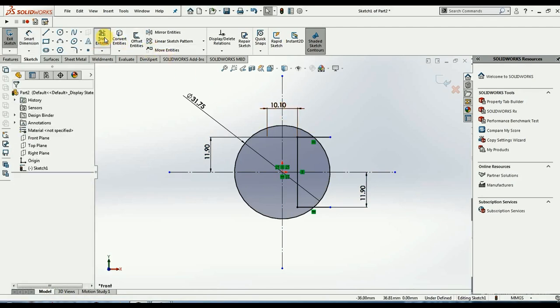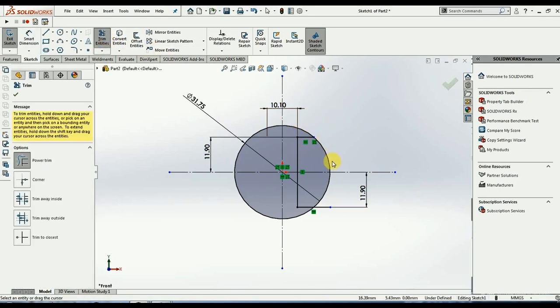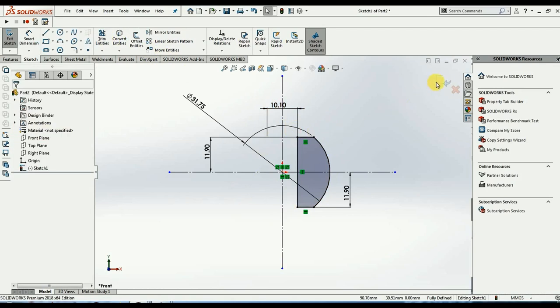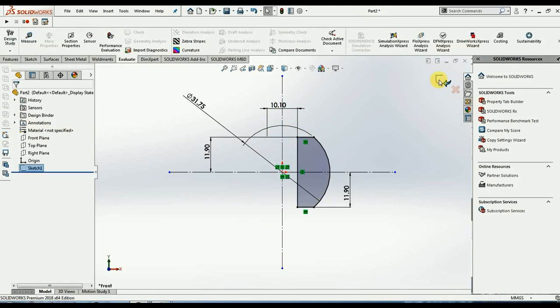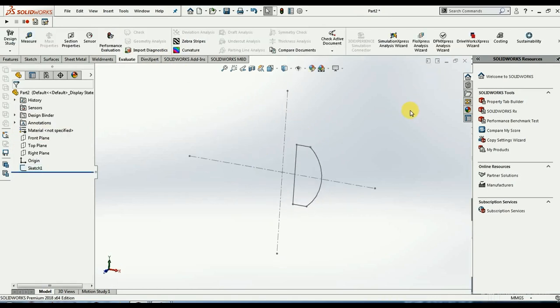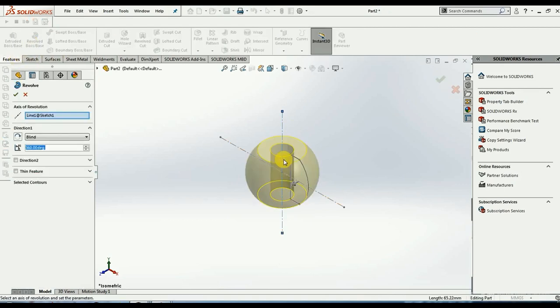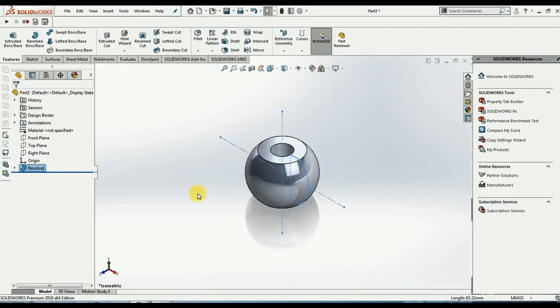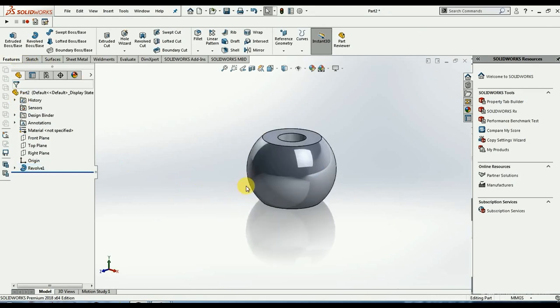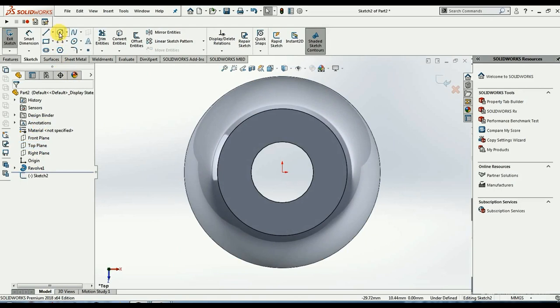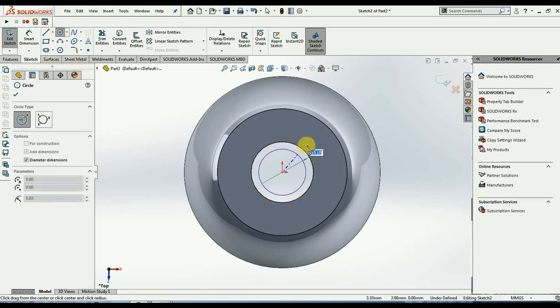Working with the toolsets is also very easy and comfortable, so that designers don't have to stress themselves working in SolidWorks 3D CAD, and they enjoy designing. See how fast I completed my design. After completing the 2D sketch, you can see that since it is a cylindrical component, I revolved it through 360 degrees. In case we need any additional projections, they can also be easily done.